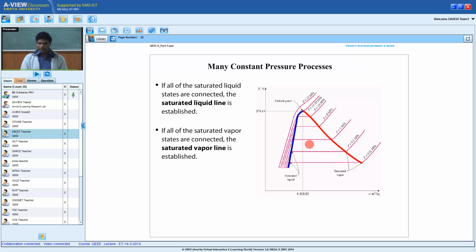If you take a combination of pressure and volume which is here, this has to be a mixture of liquid and vapor, or water and steam. It is impossible for this combination of pressure and temperature to be superheated. So that's how there is a region in which you can have these combinations occurring.